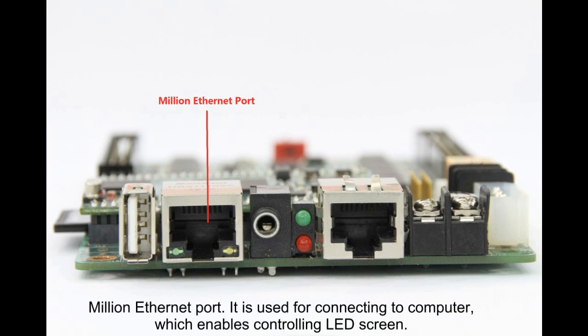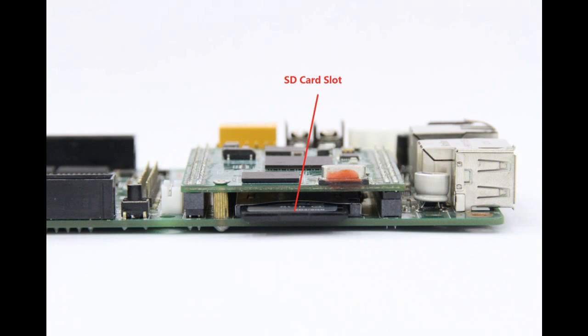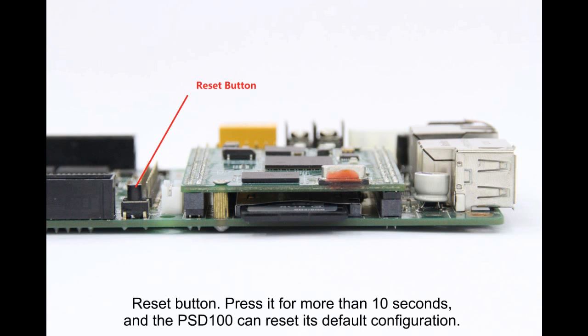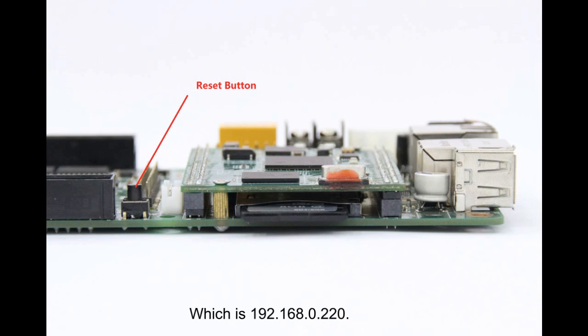Mini Ethernet port is used for connecting to computer, which enables controlling LED screen. USB port is used for supporting U-Disk plug and play. SD card port is used for supporting SD card plug and play. Reset button. Press it for more than 10 seconds, and the PSD100 can reset its default configuration. Usually it's used to restore its default IP address, which is 192.168.0.220.